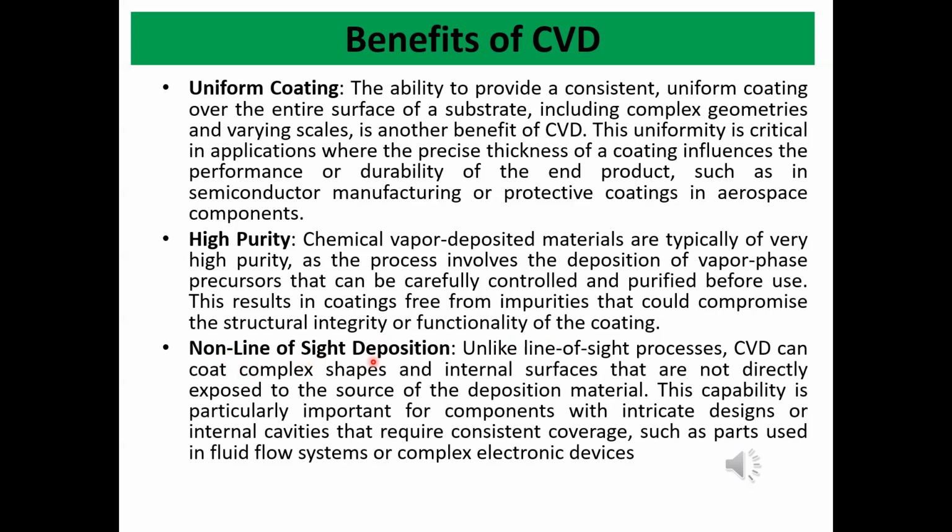Non-line of sight deposition. Unlike line of sight processes, CVD can coat complex shapes and internal surfaces that are not directly exposed to the source of the deposition material. So using CVD processes, we can even develop films on the inside of the materials, and those objects may have complex shapes.